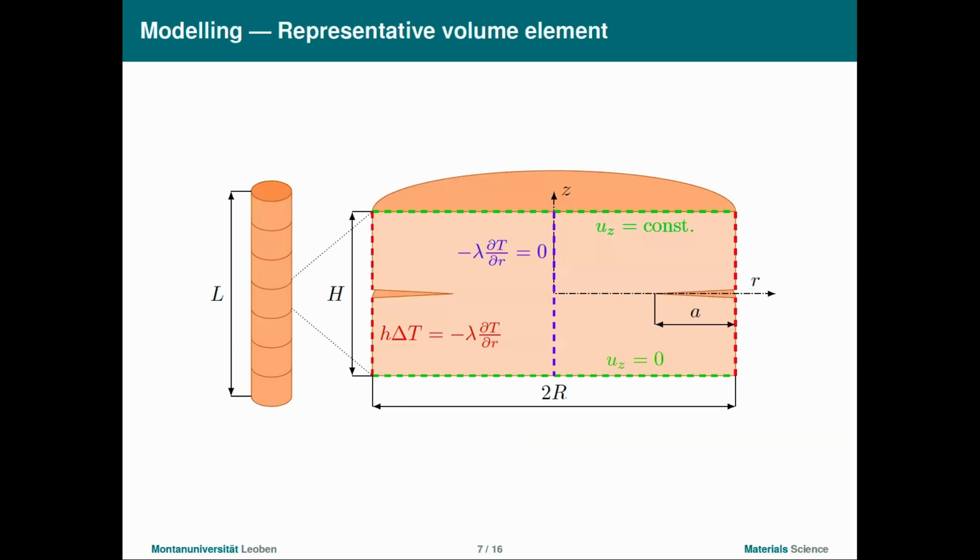And the hypothesis is if we put compressive stresses on the surface, we will get higher temperature differences. If we have tensile residual stresses on the surface, naturally it will fail with less load. And we also exploit the observed phenomenon that the crack, when it initiates, and it has now geometry like these rods, it's not some disc or whatever, it will have uniform spacing.